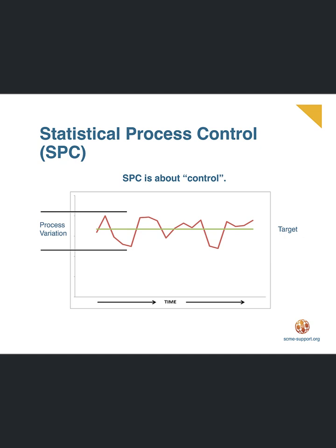This statistically based process information provides a greater understanding of the process by providing a graphical interpretation of the variation in the process. All processes have some variability over time, and that's what SPC does, is show the state of the process over time. There are two terms that you heard when we described SPC that are the basis of SPC. One is variation, and the other is data.